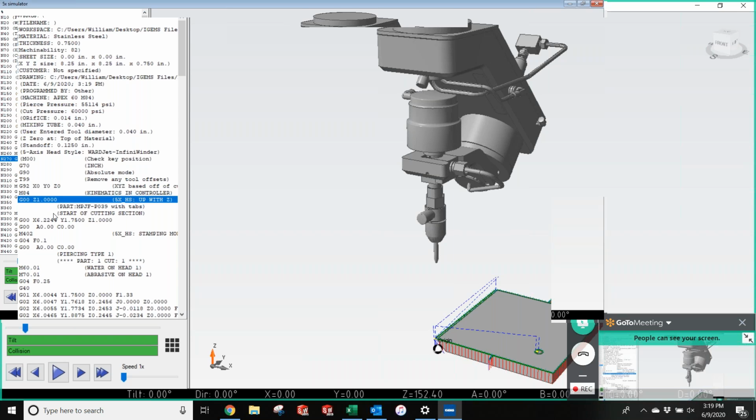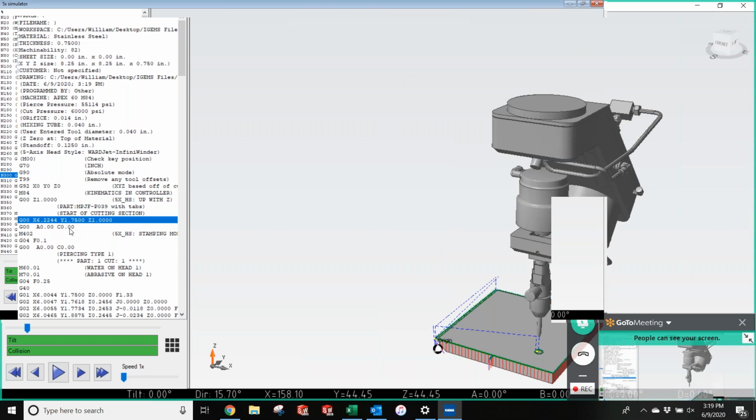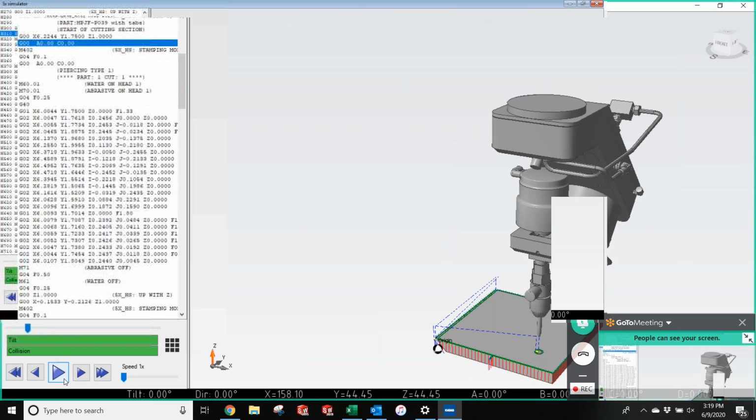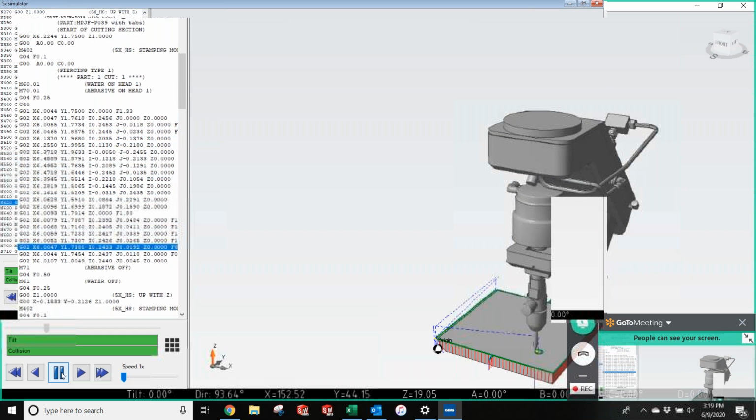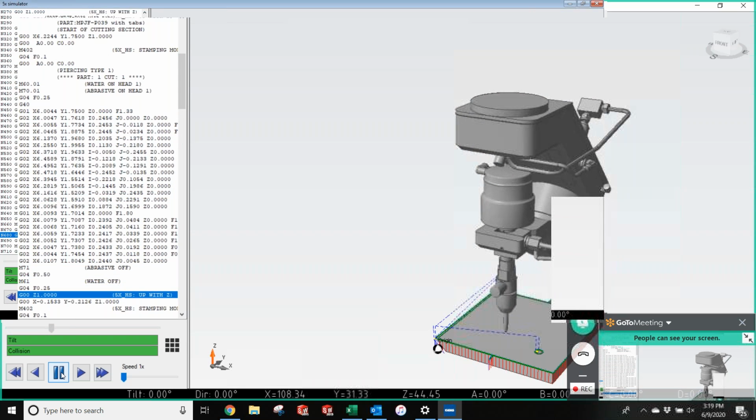Because if that wasn't in there, IGEMS has it going all the way to the top of your Z-axis travel. So the beginning of every program, it would go up like 10 inches, which I found that most people didn't like. So we'll lift 1 inch and then rapids over and does its thing. And then we lift up the inch.